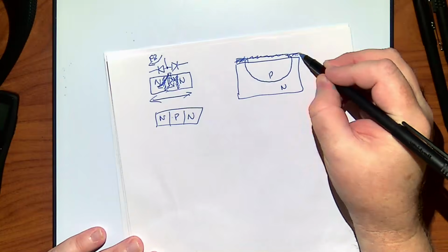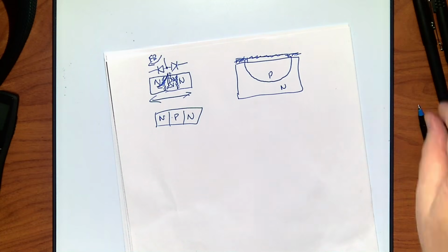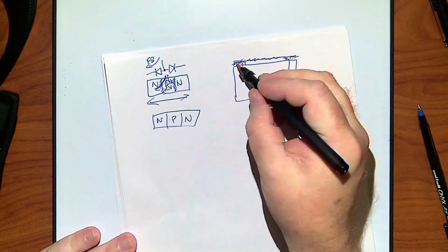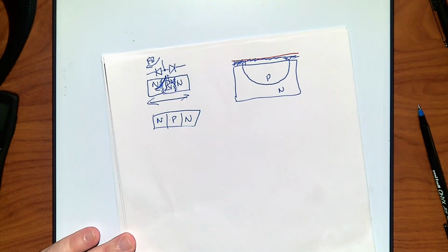This is now all gone, and I just have my material here. Then I could do the same exact trick again. I could do a photoresist layer. I'm just going to show it in a slightly different color, whatever I picked up. Okay, I picked up red, right? And let's say in this case now I would do another mask, usually with light. So this is one of those tricks with shaped masks of the layouts and the shine light.